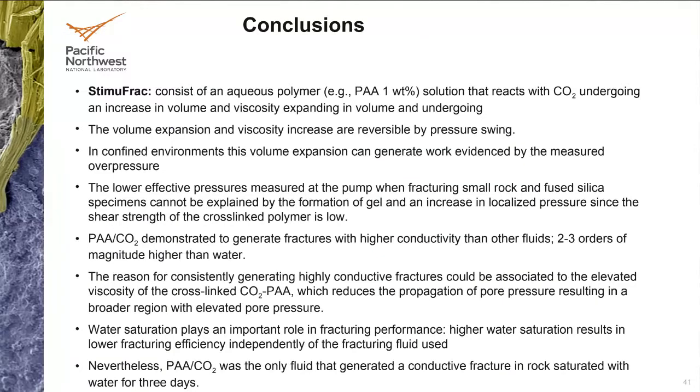So in conclusion, I presented StimuFrac. StimuFrac is a polymer solution that reacts with CO2. That's why it's a stimuli-reactive polymer. It expands in volume. That expansion in volume, as well as the increase in viscosity, is reversible in nature. So it can be used to fracture, and then that polymer solution can be recovered for reuse in a second wellbore if possible, together with CO2.